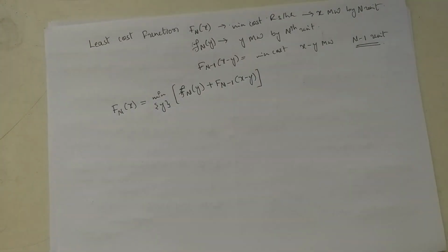In this process, the total minimum operating cost and the load shared by each unit of the optimal combination are automatically determined for each load level. So there is no need to use the exact coordination equation to find the minimum operating cost as well as the optimal load shared between the units.